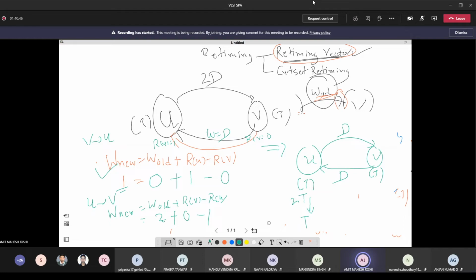So that is the base case, as I said. On every edge, when you get a delay, that is the base case for you, and that's what you achieve. And once all the edges are having a delay, then it is up to the node. Now the node execution delay is what we consider as the critical path. So the critical path will be the maximum time taken by a particular node. So here if I consider both the nodes are taking the same time, that means the critical path delay is T. The best I can get for this particular graph is this one, and that's what I have achieved. So from twice T, I have reduced it to T with this concept.